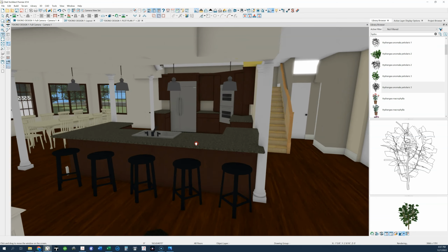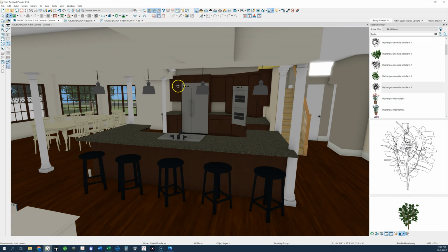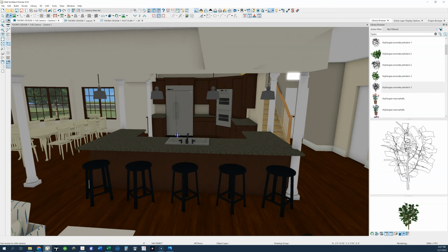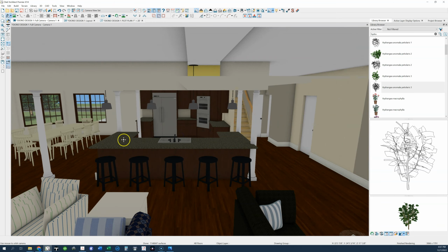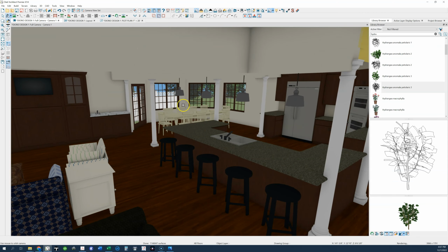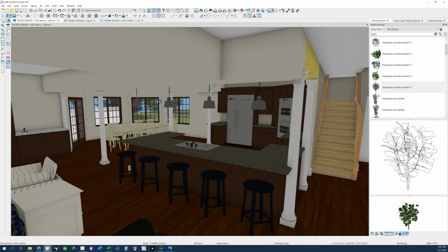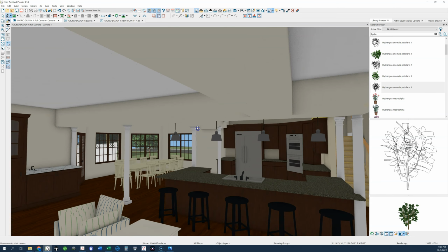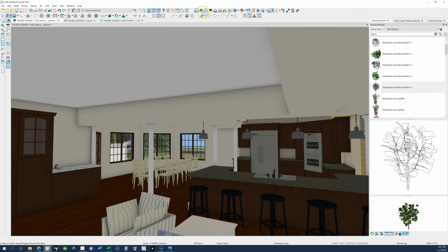I took down the walls now. These columns represent where there are beams ending and there are supports going down into the foundation. So this wall can be taken down as long as there is a column here. There is another, honestly, there's beams all over this design because of the way the original structure was built.